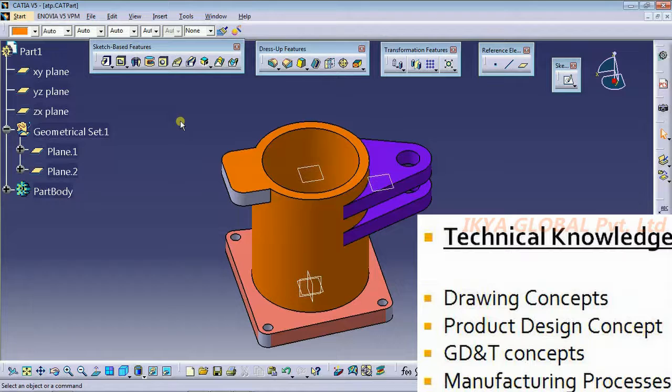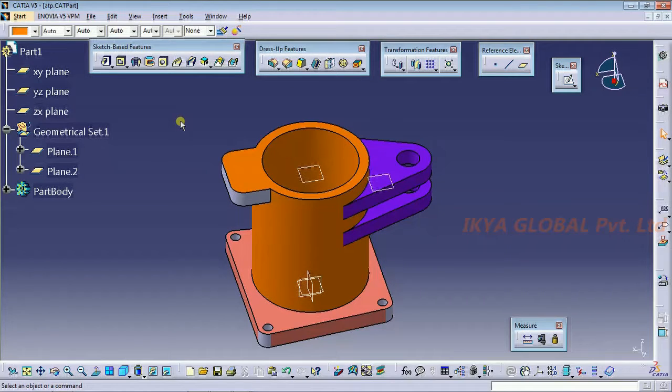If you want to create a hole on the sheet metal, then from the edge, how much space do you need to give? Bend radius: how much bend radius do you need to prefer? Outer radius and inner radius calculations, K factor. These are all design considerations that come under sheet metal.